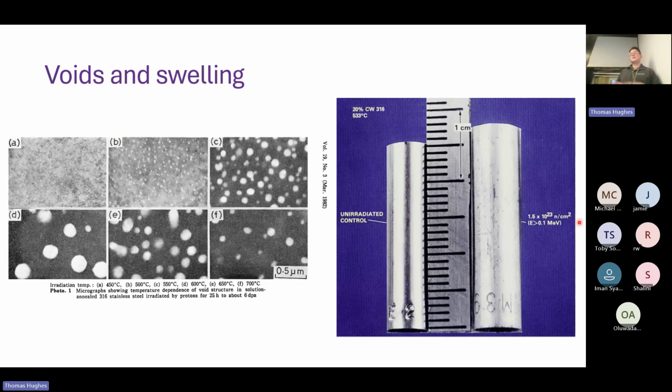And these voids will grow, which means you've got parts of your material with no material in it, which then will lead to a size change, but also your material becomes worse because there's essentially less of it in the same volume. So you can see the size of your part has drastically changed, which is something you definitely need to consider when you're designing parts. They might not fail, but they might just grow and the geometry will change and they're not fit for purpose anymore.